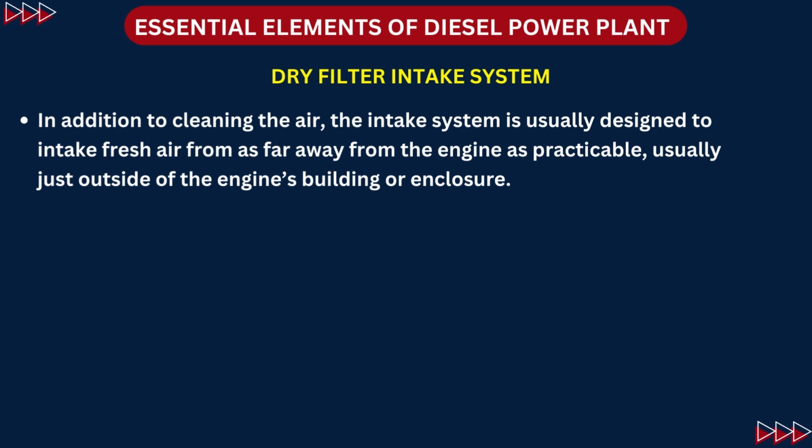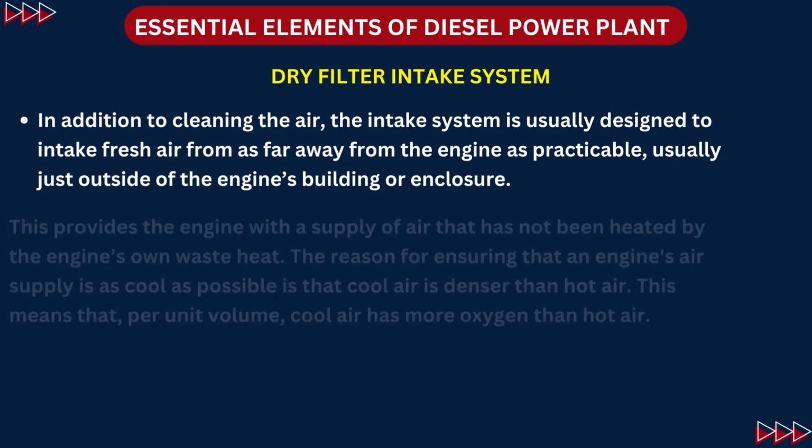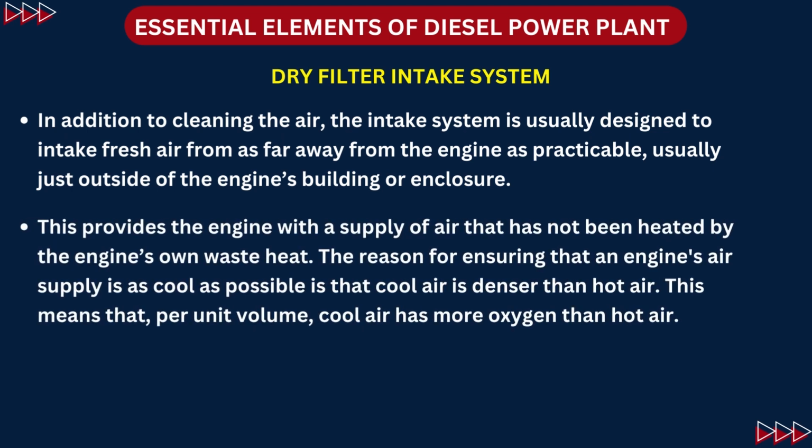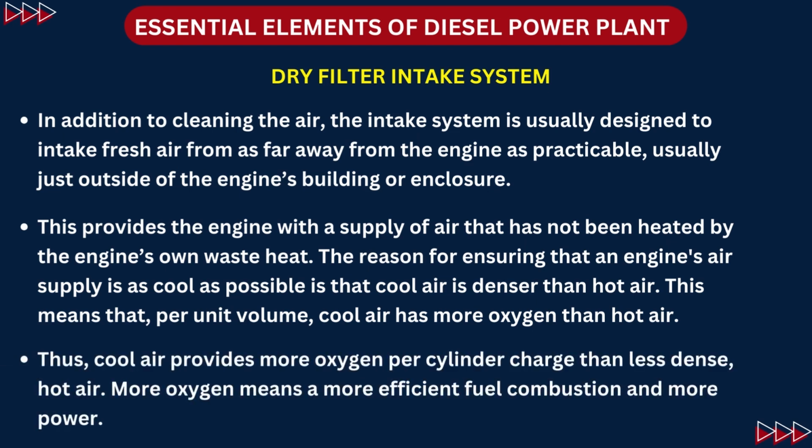So, usually just outside of the engine's building or enclosure we can do it. It also provides the engines with a supply of air that has been heated by the engine's own waste heat. So, this is the reason for ensuring that an engine's air supply is as cool as possible, because cool air is denser than the hot air. What does it mean? It means that per unit volume, cool air has more oxygen than the hot air. So, this cool air provides more oxygen per cylinder charge than less dense hot air.